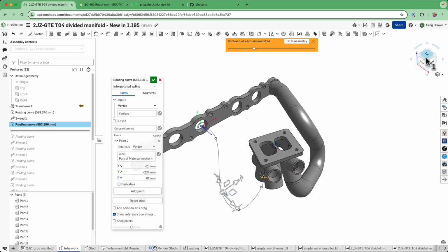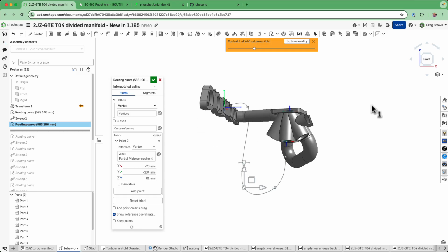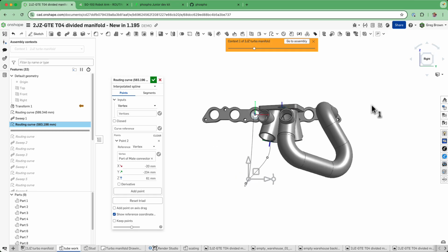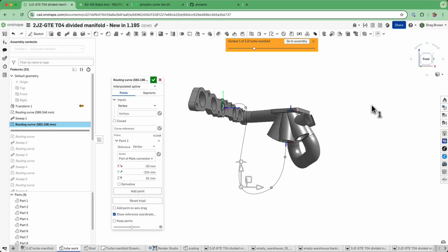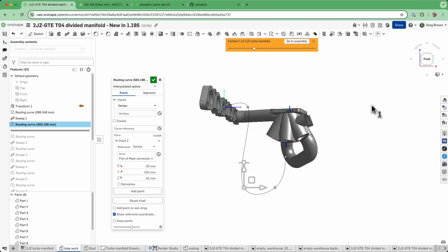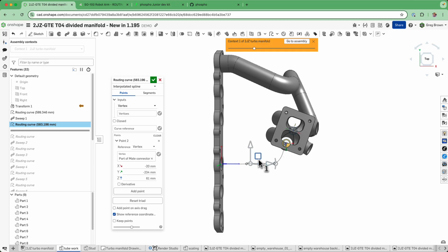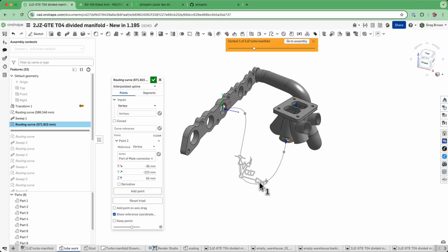But the tip I actually wanted to show you was, if you look at the top view and hit Shift arrow, we go in 90-degree moves now. So I can look at the right, I can look at the front, I can look at the top. And you get a good idea of the routing of a 3D curve like this if you go from these three kind of canonical directions. And that's why it's very convenient then to be able to move this in those planes. Just go like that, move it around here. Now we're moving it in the XZ plane, and we're going pretty well.